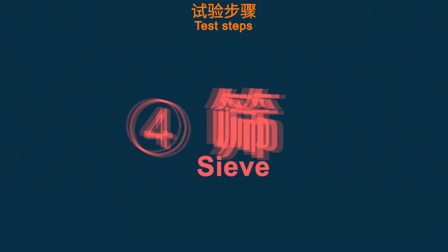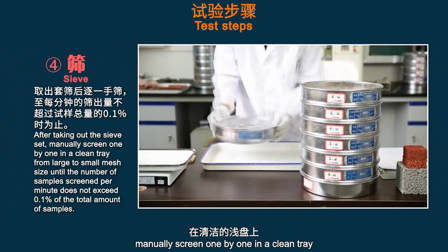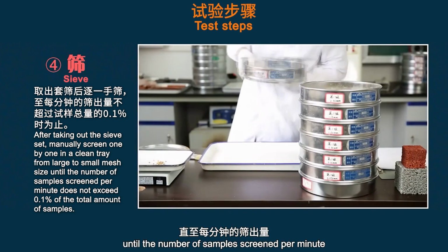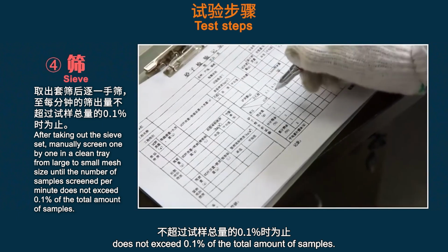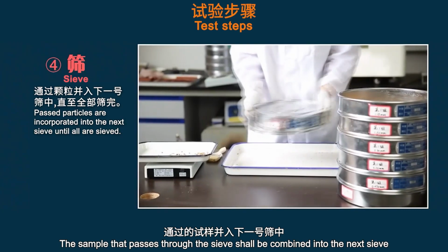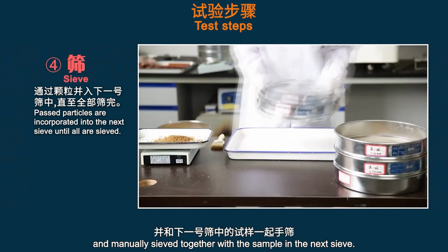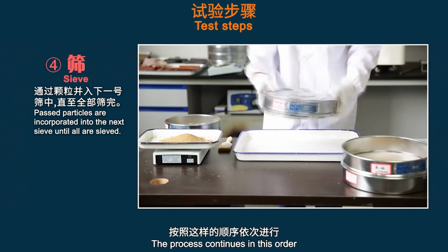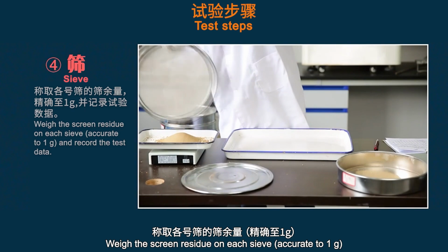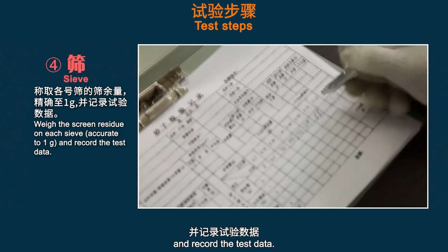4. Sieving. After taking out the sieve set, manually screen one by one in a clean tray, from large to small mesh size, until the number of samples screened per minute does not exceed 0.1% of the total amount of samples. The sample that passes through the sieve shall be combined into the next sieve and manually sieved together with the sample in the next sieve. The process continues in this order until all the sand is sieved. Weigh the screen residue on each sieve, accurate to 1 gram, and record the test data.